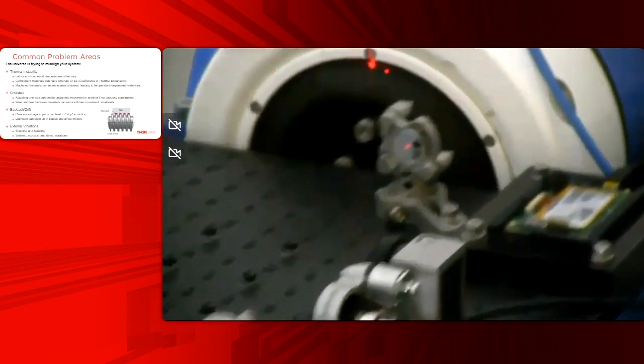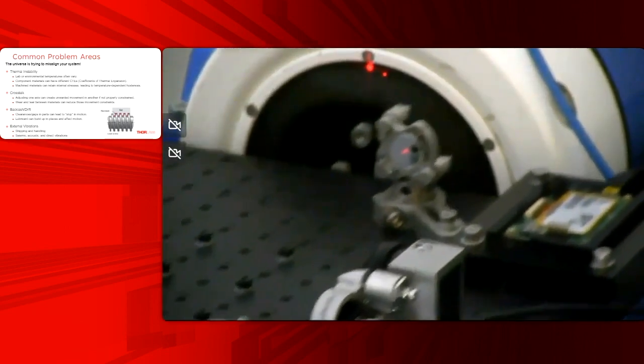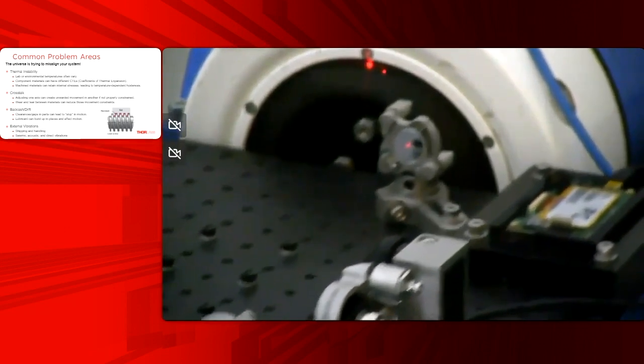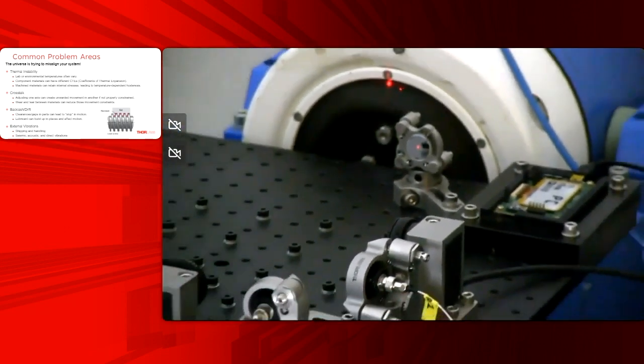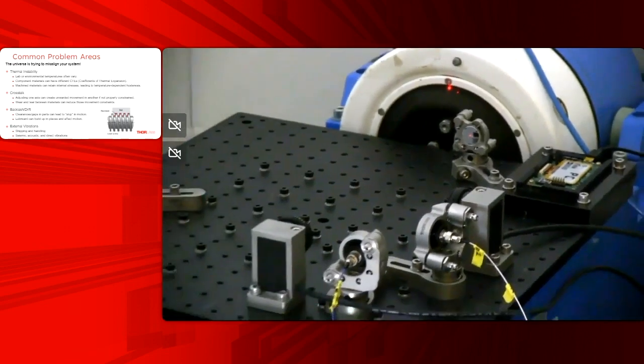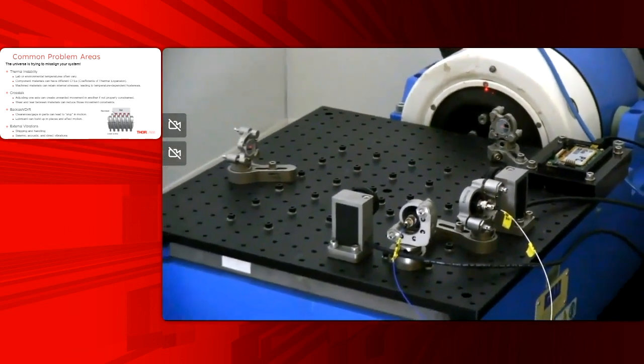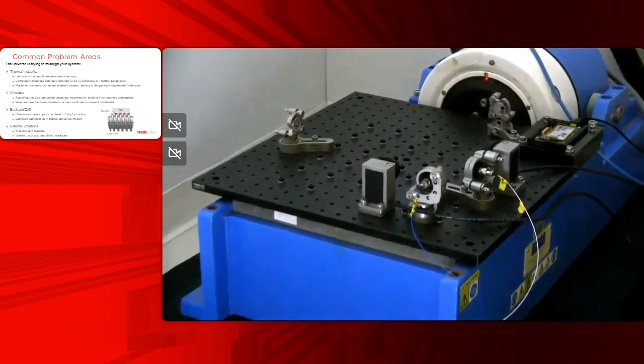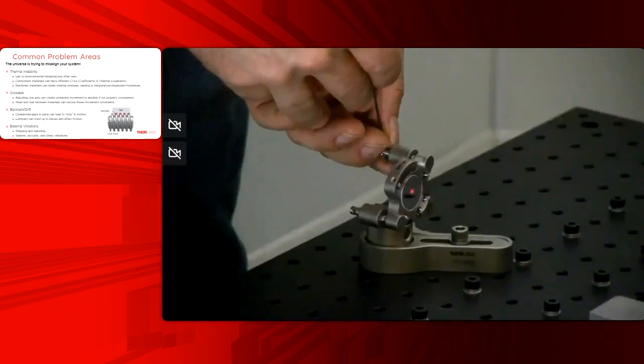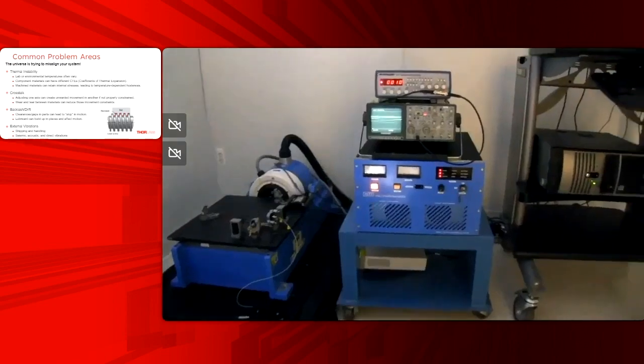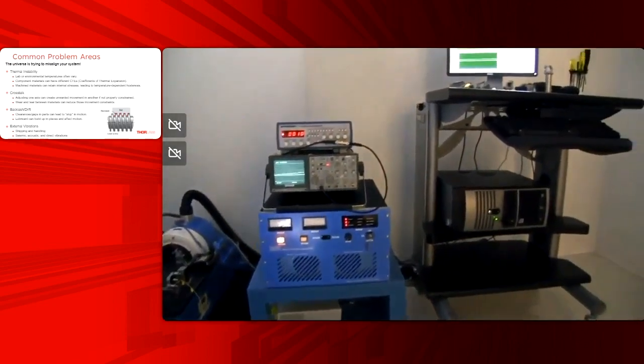So as the video plays, for vibration testing, we put two mirror mounts mounted on 1-inch posts and secured them to a breadboard with clamping arms. Collimated lasers were then reflected from those mirrors onto two lateral position sensing detectors on the same breadboard to detect changes in the beam's pointing stability over time.